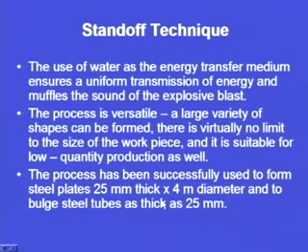So, this is a versatile process. The shape is no limitation, the size is no limitation. Moreover, another important point is that low quantity production is also possible using the explosive forming technique.